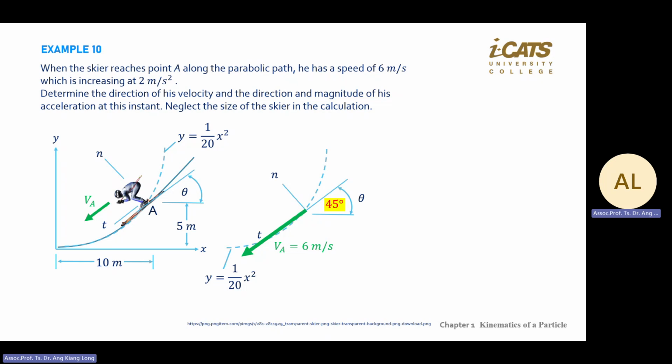No, check the equation that you use. I suspect you used the wrong one. The one that you use is a bit ideal, but you need to use according to the design handbook, including the K value, the efficiency for motor, efficiency for fan. You need to consider that. If you do not consider that, then you might not get the final air speed that you need.